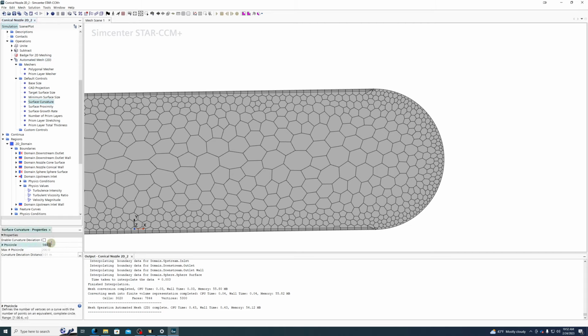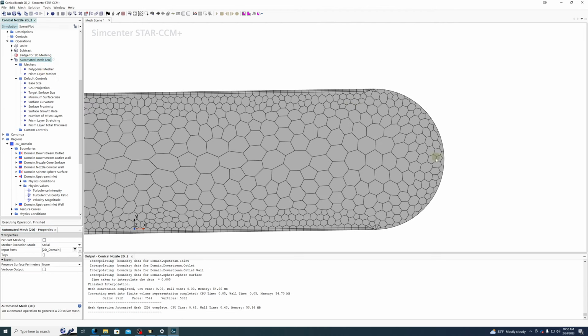So realistically, 36 is usually okay for most applications. I'm going to go ahead and just leave this at 36, but you can tune that up or down depending on how accurate this circular arc needs to be. I mean, to me, this looks pretty darn circular as it is. You really don't need to refine that any. But if you wanted to, you could refine that. And there's even a little checkbox here to say, hey, the maximum distance you can move off of this circle is some amount.